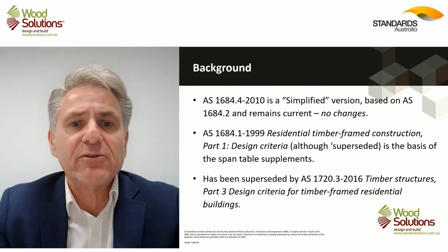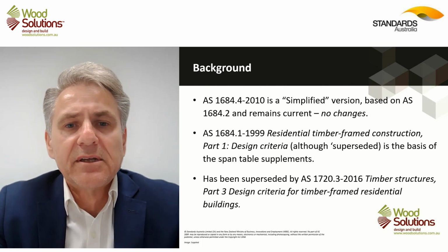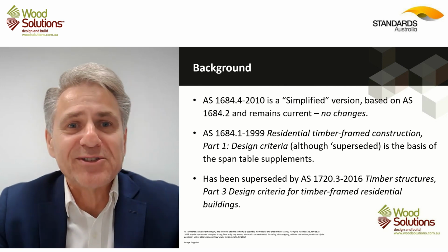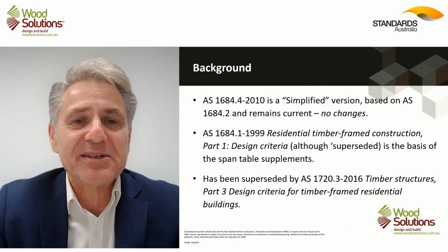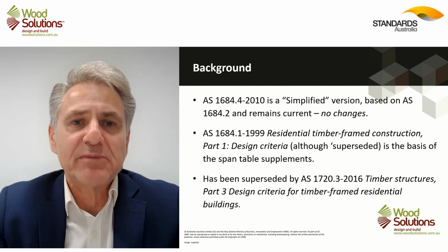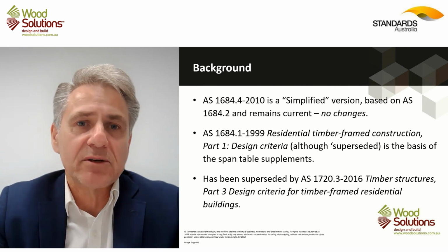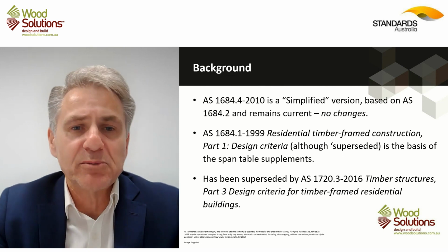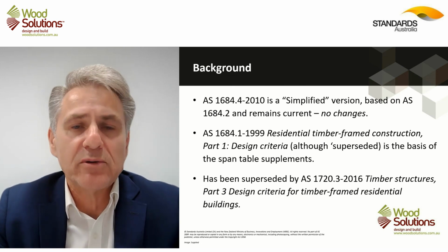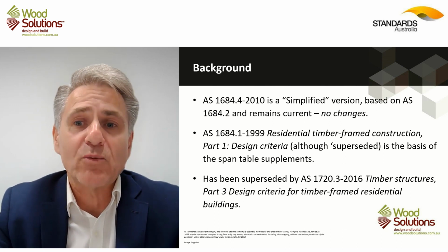But because things have evolved, there's a new standard that's been developed, AS 1720 Part 3. When I say new, it's 2016, so it's not all that new, but it was an evolution of the 1999 edition, updated in accordance with current design practices. So if a structural engineer is going to design a beam to be used in your timber frame house, they would turn to AS 1720 Part 3, not AS 1684 Part 1.